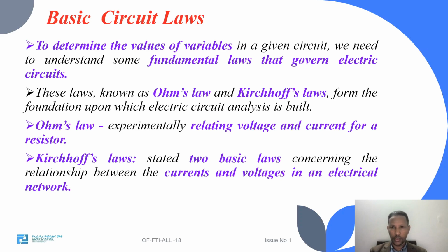So today we'll see the basic circuit laws. Under this, we'll see two very important circuit laws, that means Ohm's law and Kirchhoff's law. Why are they very important in electric circuit analysis? Because they are the fundamental laws. That means every circuit analysis will depend on these two laws. Ohm's law experimentally relates voltage and current, that means the relation between voltage and current for certain resistive elements.